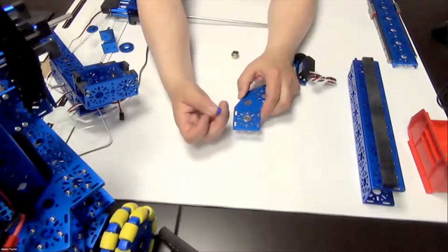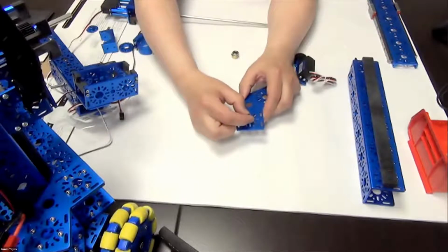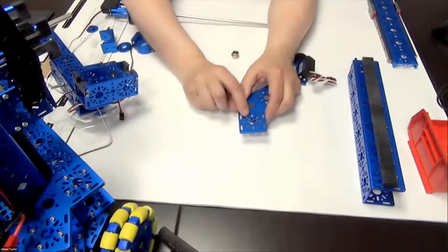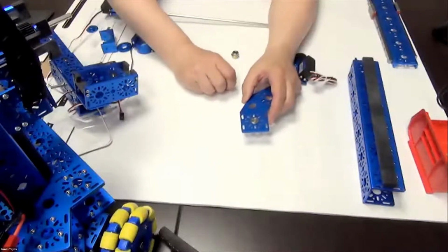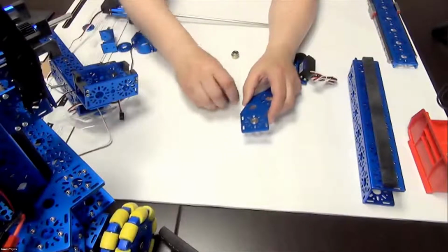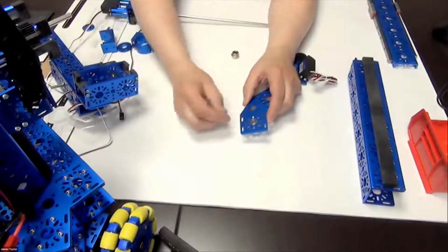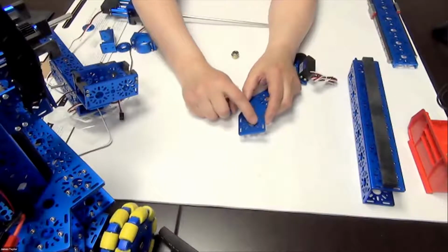Now, so that you can see it, I've got a large spacer here. The key behind the spacers is that you're going to use 1mm spacers on the top of these flange bearings or anywhere where we can get that metal-to-metal contact. So where we have metal-to-metal contact with the bearing and a shaft collar or anything else, we put in a spacer.